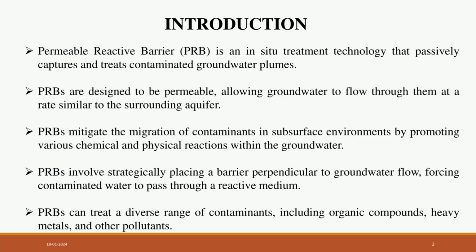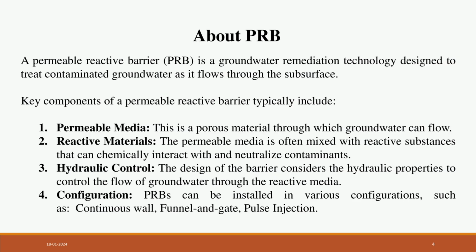They involve strategically placing a barrier perpendicular to the groundwater flow, forcing contaminated water to pass through a reactive medium. PRBs can treat a diverse range of contaminants including organic compounds, heavy metals, and other pollutants like insecticides, pesticides, nitrates, nitrites, etc. So moving to the next slide, what is PRB and its key components?